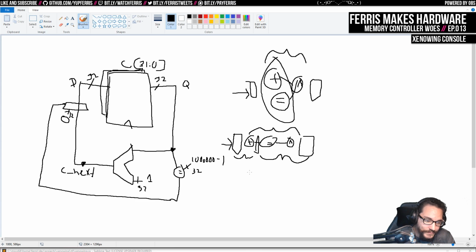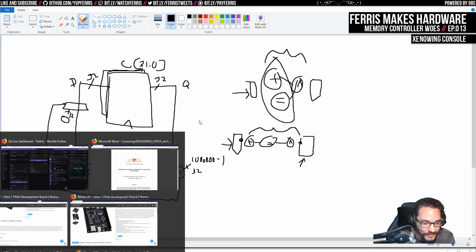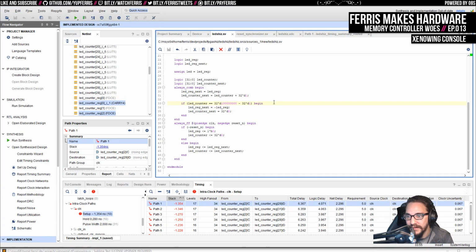And maybe that's fine. You can also mark a path as being a multi-cycle path and just say that, instead of actually adding a register here, I'm not even going to look at this input for another 2 cycles. Or instead of in the same cycle, I'm going to wait another cycle before I sample the output here from here. So you'd mark the path between this register and this register as a multi-cycle path that's 2 cycles long. And then it will also lay those out far apart, for example. It can do that. So there's a lot of cool stuff that these tools can do.